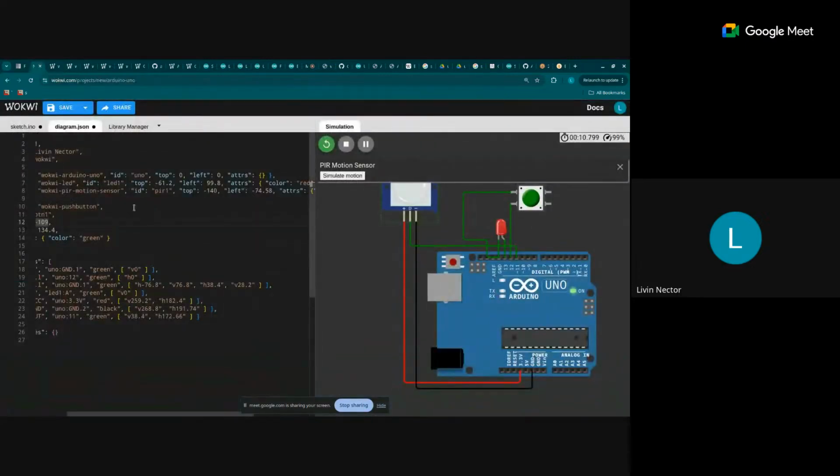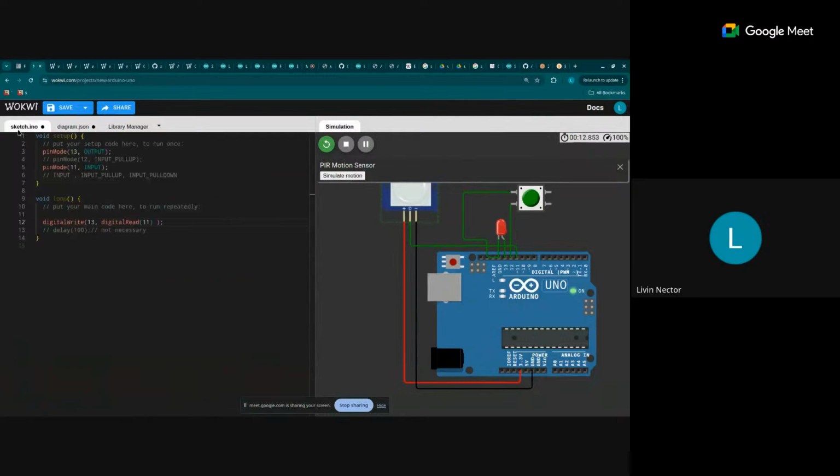So you got the basic idea of how GPIO works, right? Input, output, high and low. Digital GPIO is about that, and you have analog devices. In digital GPIO, the values are zeros and ones, and in analog, you will have values ranging over a certain number of bits. So analog will have many values, right? Instead of 1 bit, your value will be some 8 bits or 16 bits.